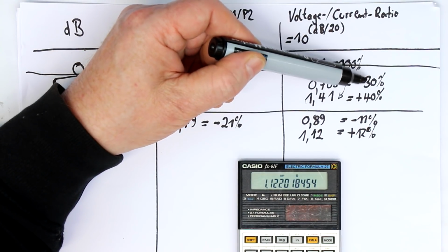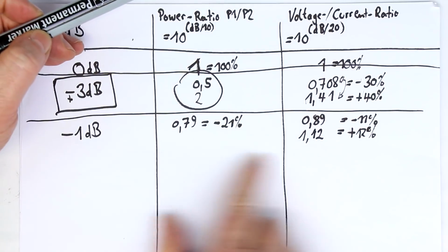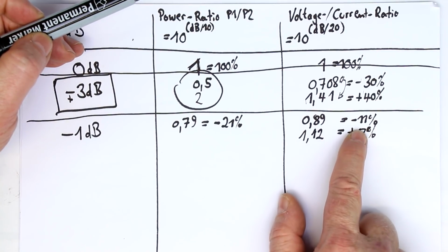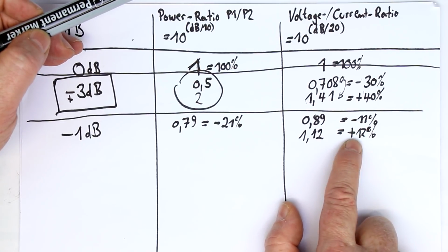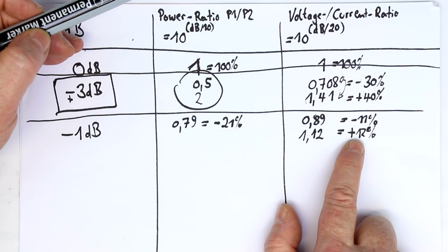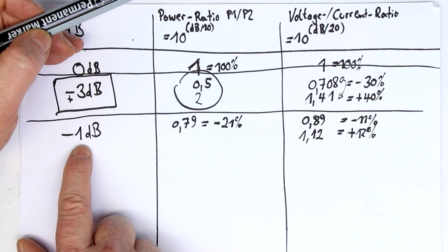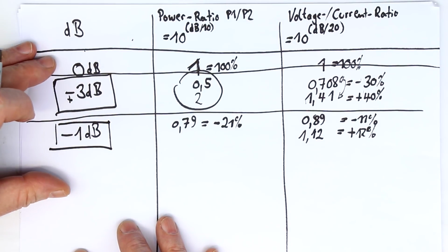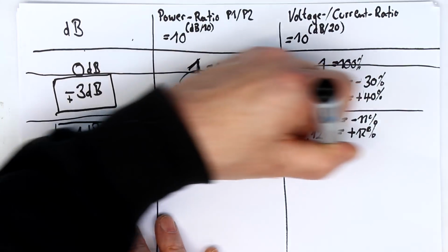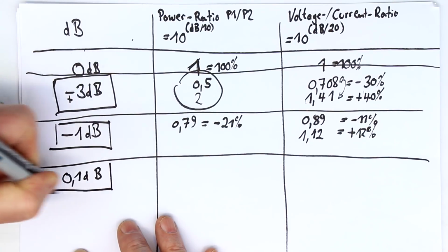So you can see here at the minus 3 dB we still had, between the minus and the plus, if we take it in percentage, a substantial difference. But if we go to smaller values, the difference in percentage is nearly the same, and we can round both values to 10%. And that's also easily observable on your oscilloscope and easily measurable just by eyesight. A 10% drop in level gives you minus 1 dB. And so that's the more stringent definition for a good frequency response. And as an exercise, you should also do this for ultra high precision measurement, test and measurement equipment.